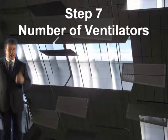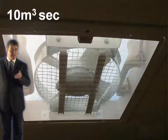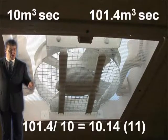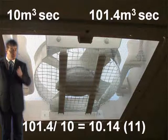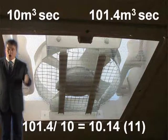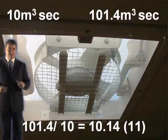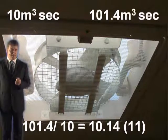We need to work out how many fans we need. Now, we know that the proposed fans have a capacity of 10 metres cubed a second. We know the volumetric flow rate is 101.43 cubic metres a second. So if you divide it out, you need 10.14, or 11 fans. You're going to need at least 11 fans in each reservoir to satisfy that volumetric flow rate.